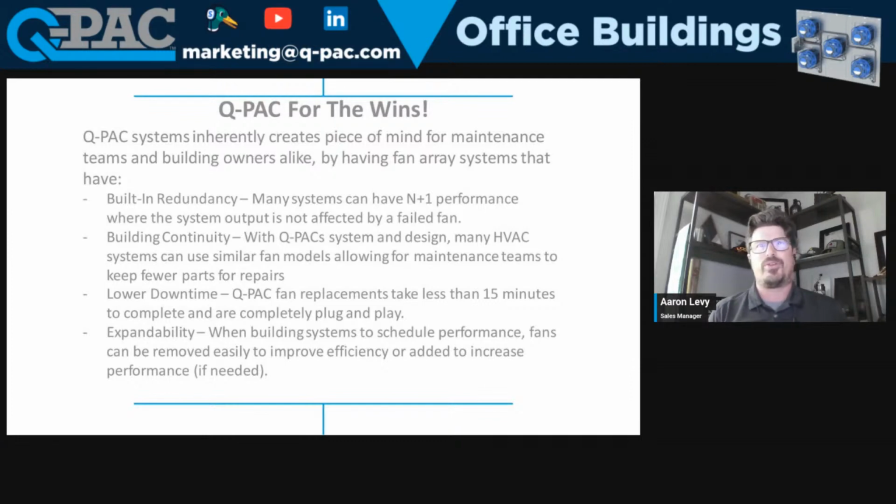And one of the things that we don't really talk about a lot, but I wanted to focus on because we're talking about office buildings, and a lot of times we go off engineering schedules, is the expandability and the collapsibility of our system. If we over design a system, say it's an 8-pack system, so roughly 40,000 CFM, and that turns out to be 30,000 CFM, it's very easy to remove 2 fans out of the system to get your efficiency higher up, put 2 blank off plates on, and then have 2 spare fans.